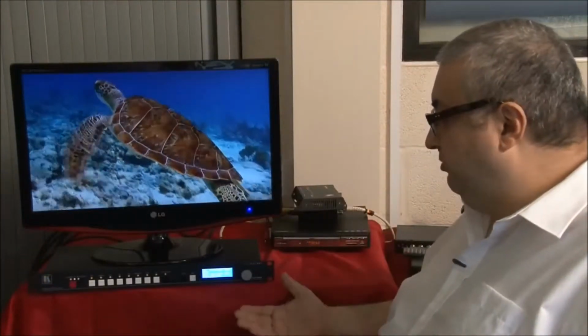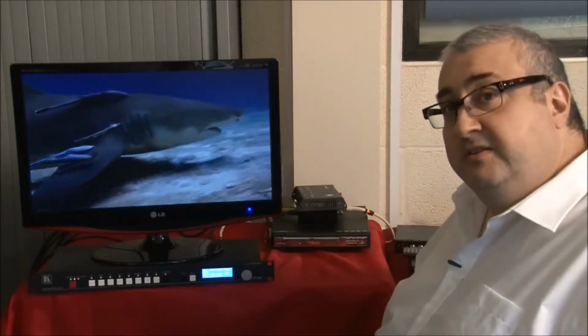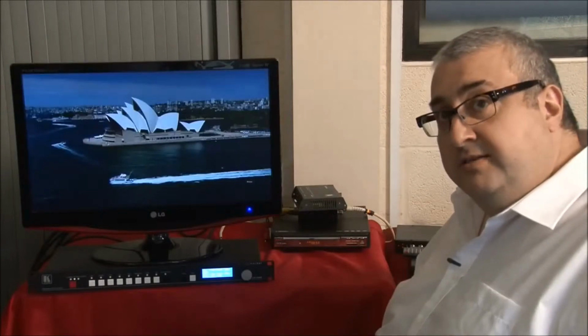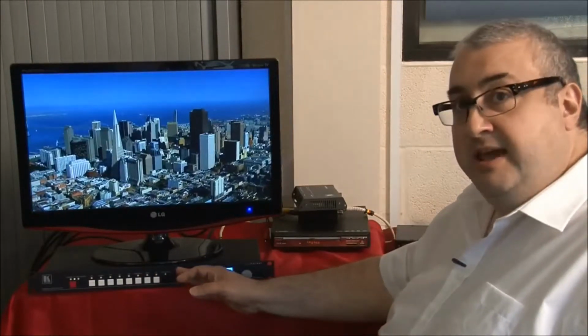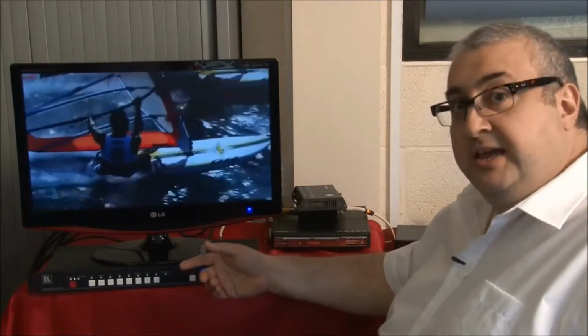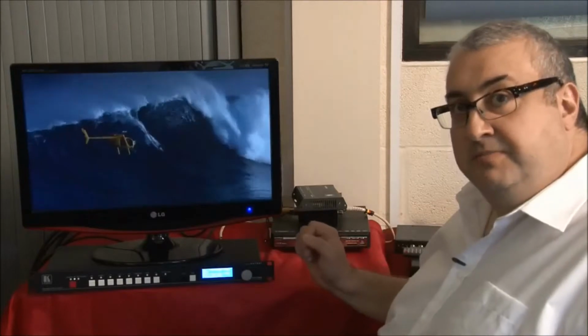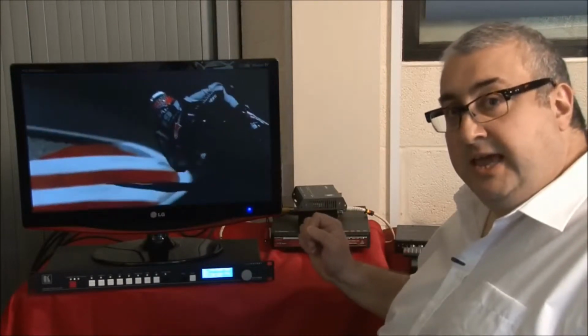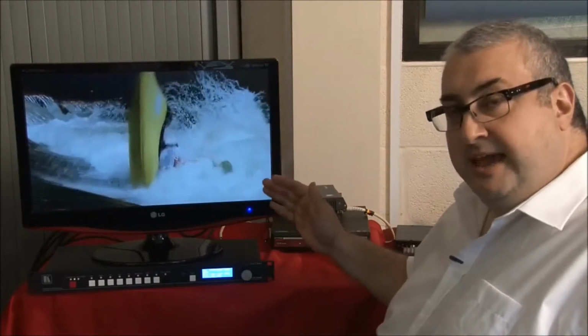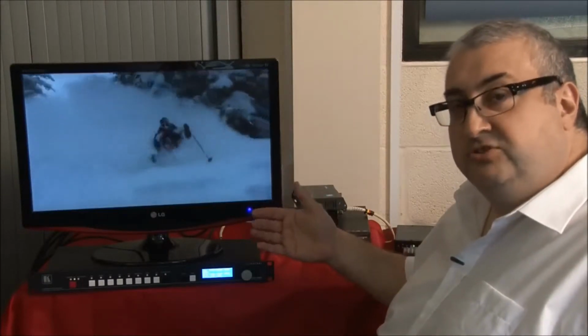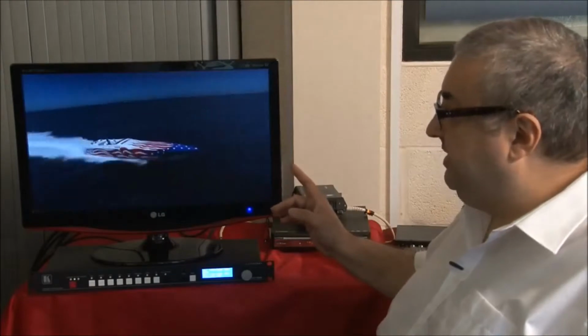So in LED mode or projector mode, VP-794 is optimised for low video delay or low video latency rather than clean switching. This means that when you change input channels, the output has to resync because the vertical sync of the output is dependent on the vertical sync of the input. That minimises video delay and ensures no tearing of the picture if the display is in camera, on set, on a TV set or at a concert. But it doesn't give clean switching.